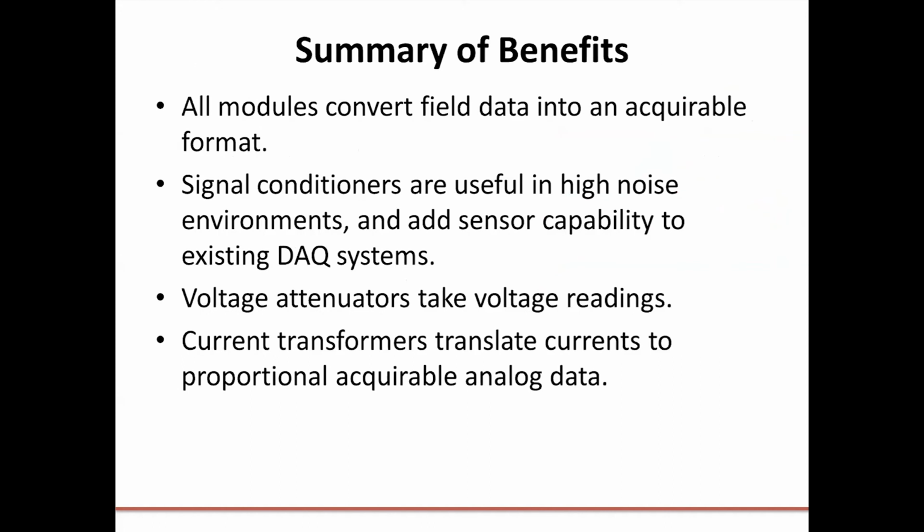So that about wraps it up. Now that we've had a look at our products, some of their applications, gone over basic terminology and functions for all three types of devices, I'll just summarize the benefits of each. While each type of product produces a similar outcome, that is, changing an input into a readable output, they all have their own unique applications. Signal conditioners are a great fix for adding sensor capability to an existing DAQ system. They're also great for high noise situations and in applications where you don't need a specialized DAQ module.